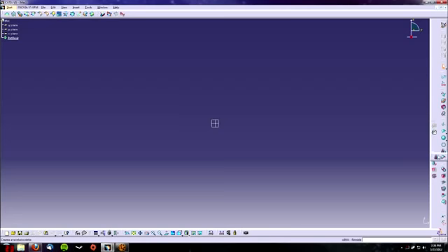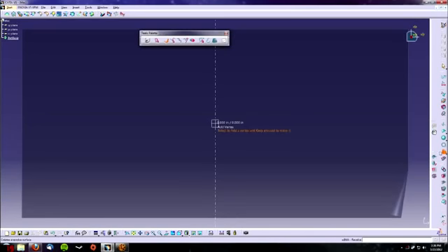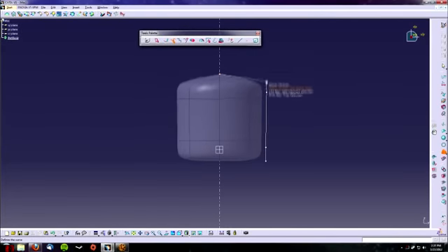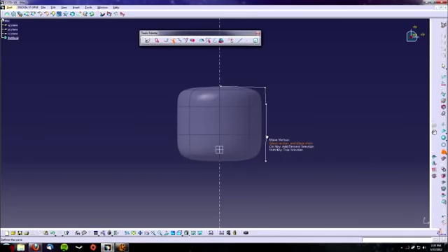So first, we're actually going to use the revolve command to create the cylinder, which will be the shape for his head. Alright, so go ahead and just make a similar kind of curved cylinder. You can edit your points using the Edit Points command on the Tools palette, and you can get a little small shape off of it. Nothing too crazy, just a simple curved cylinder of sorts.